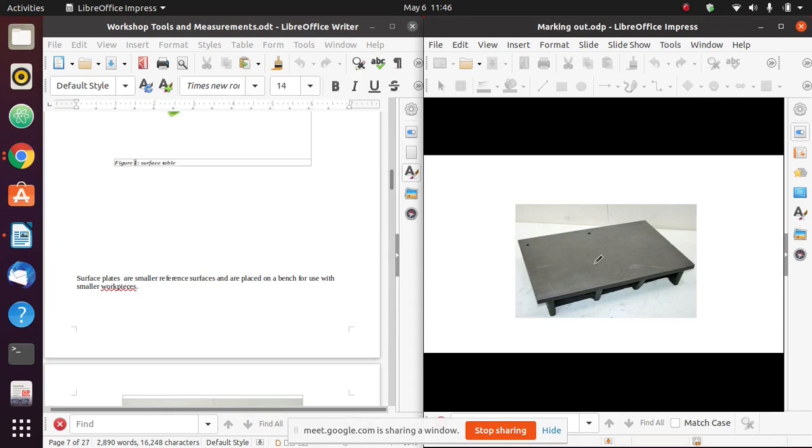If it is not flat, then some parts of that workpiece will have the red paint, and some parts will not have. Meaning that workpiece is not purely square. It is not square at all.